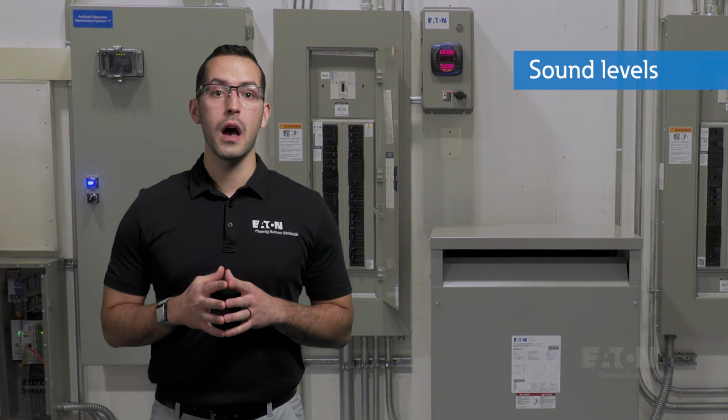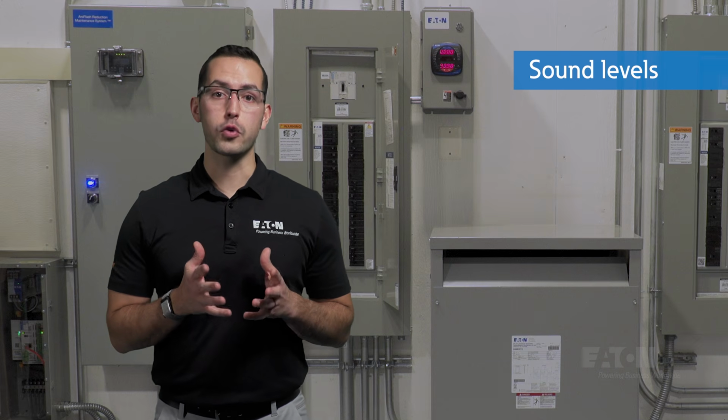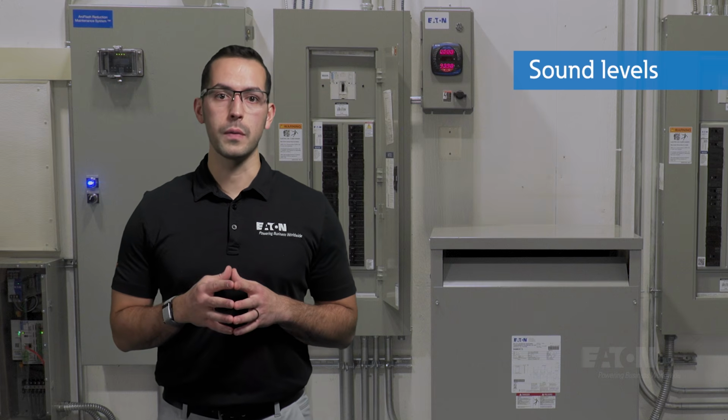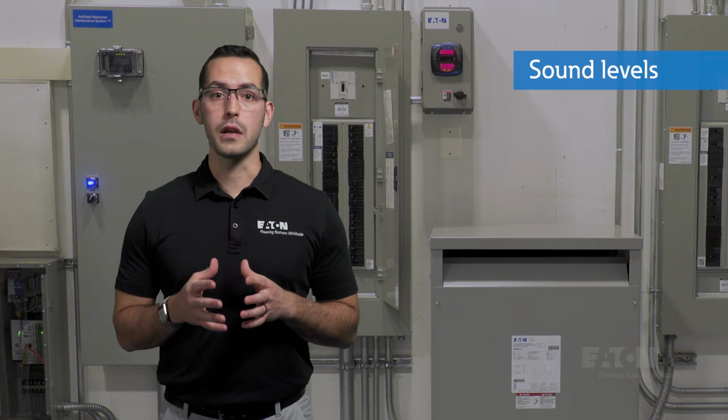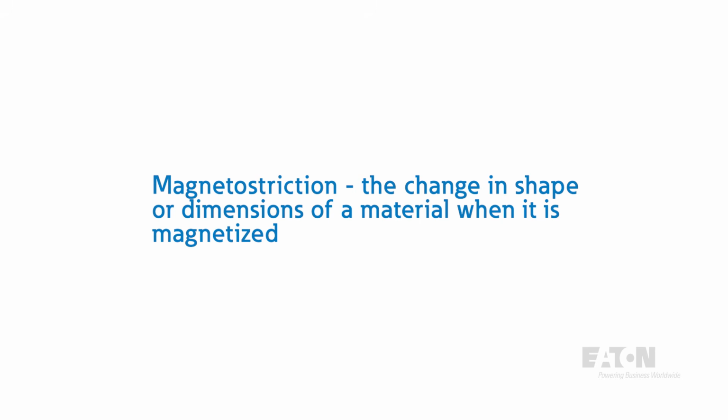Sound levels. Under normal loading and operations, transformers will have an audible sound level. This is caused by multiple factors, primarily due to the magnetostriction of the core material and other phenomena associated with the magnetic fluxes involved. Magnetostriction is the change in shape or dimensions of a material when it is magnetized.